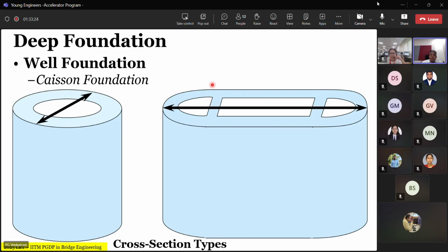But normally in a space like this, you cannot have two cranes sitting and operating. This is not as if this is 50 meter wide. Most of it is about 10 to 12 meter dimension this way, maybe 3-4 meters clear opening like that. So in that case, these two openings, though in this sketch look wide, if there are only two openings, they're very close to each other. So you cannot operate cranes so closely. So you end up using one crane. One crane means it will grab in this and then it will grab in that.